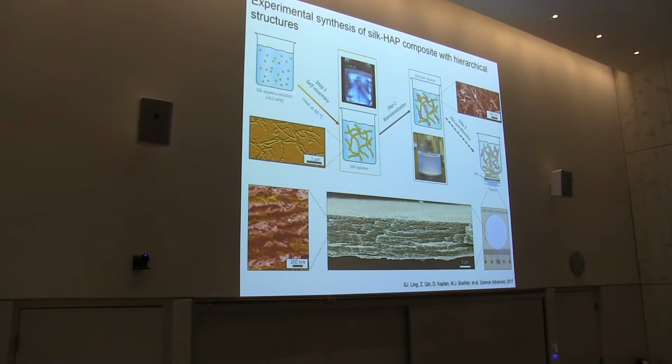So I dissolved the silk cocoon inside the formic acid solution. And then I put the hydroxyapatite together with those silk nanofibers. And then to have a very high flow rate, I put the solvent in the bottle, and then I use a vacuum to filter out the solvent, but just leave the nanofibers and hydroxyapatite at the bottom of the bottle. So I actually end up with this multi-layer structure.